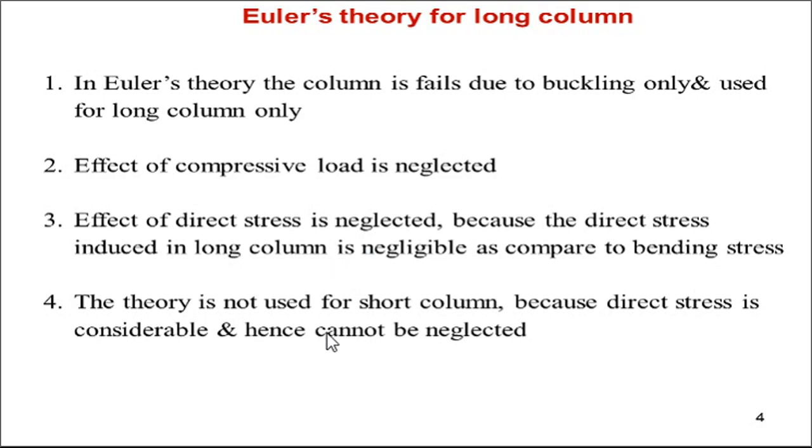The theory is not used for short columns, because direct stress is considerable and cannot be neglected. As we know, in a short column the direct stresses have significant values, so we cannot neglect them. That's why this theory is not used for short columns. It is only used for long columns, which have only buckling stresses.